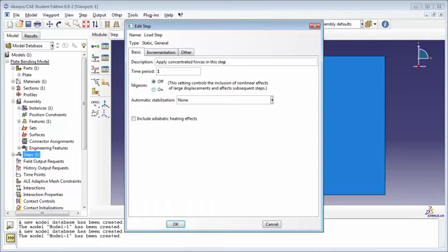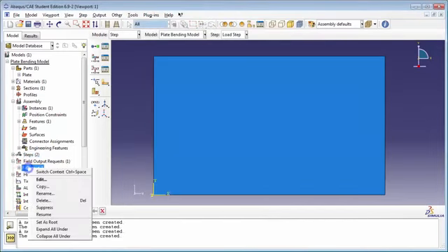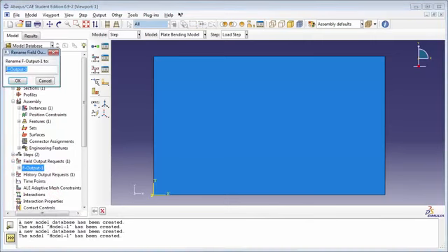This is because we can expect some nonlinear behavior in the simulation. Initially, the plate is only going to have bending stiffness, but once it's bent a little bit, we're going to experience membrane effects, or membrane stresses, which might increase the bending stiffness of the plate. We'll rename the field output, calling it output stresses and displacements, and we'll set it to output exactly what the name suggests.